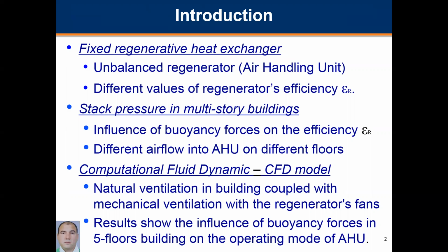Compared to industrial regenerators, which operate under almost constant conditions, regenerators in ventilation systems operate under variable climate conditions, variable temperature, humidity, and especially the pressure difference in the building. These variable conditions lead to an unbalanced regenerator, or in other words, to an unbalanced operating mode related to different values of the regenerator's efficiency.